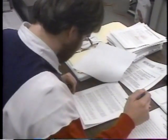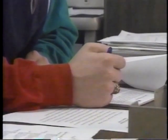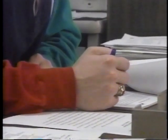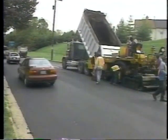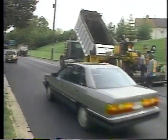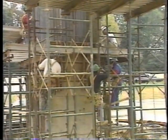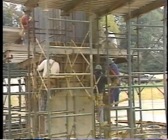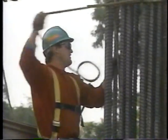Working day is the number of working days estimated for the contract to be completed. It is used on the minor contracts, intersection improvements, and landscaping. There are also recommended planning units of measure for activity groups. For roadway construction, use kilometers. For bridge construction, use 30 linear meters. And others include working days and lump sum.